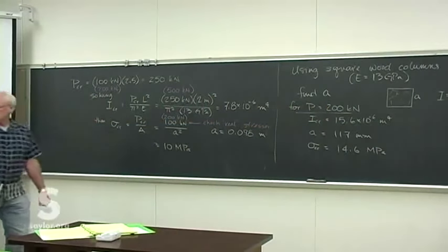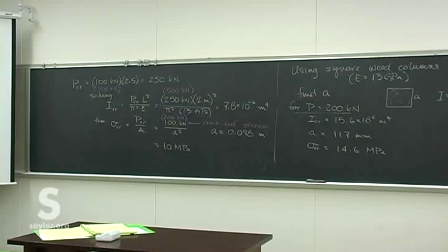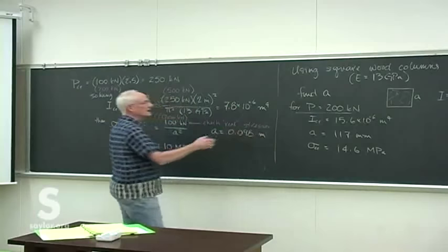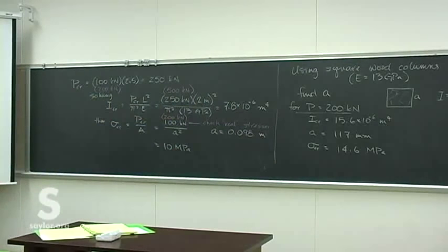So you should get 14.6, I think that's what you said, John. And that's greater than the 12, so if we really do need the 200 kilonewton limit, we're going to have to design it based on the critical stresses rather than the critical buckling.